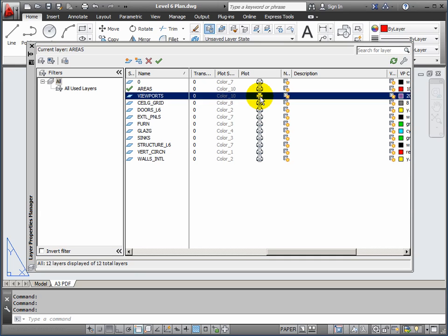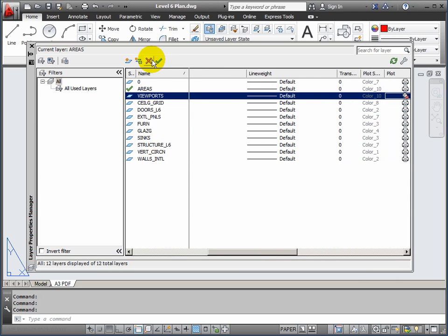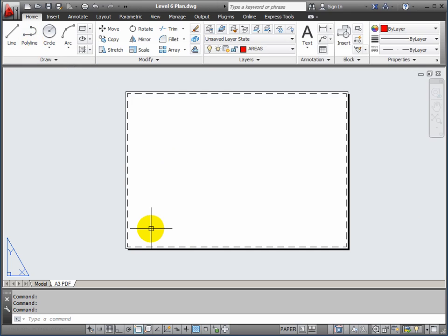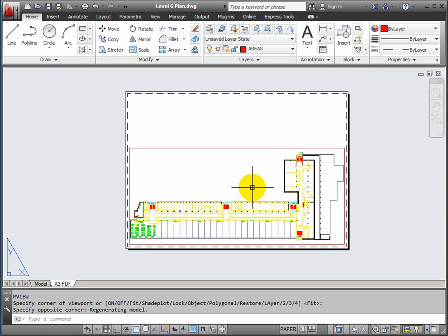And if you left it printing, you'd actually have kind of boxes around all your various bits of drawings, and it looks pretty childish. Okay, so we take the printing icon off there. Okay, like I say, don't make it current. Okay, we do that, and then we'll create a viewport using the mv command, mv, and you click, let go, move away, and click again. Okay, I'm making a viewport that's about 2/3 the size of the piece of paper. And what happens is that it automatically fills with whatever it finds in model space.